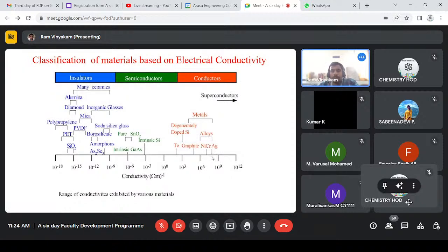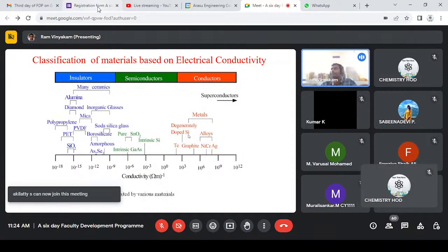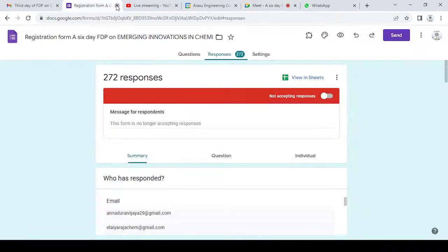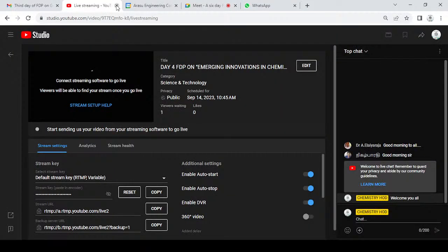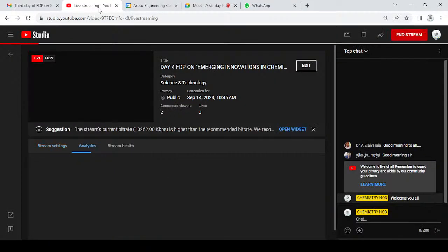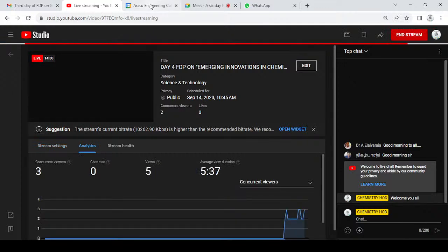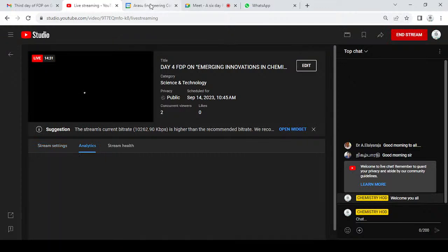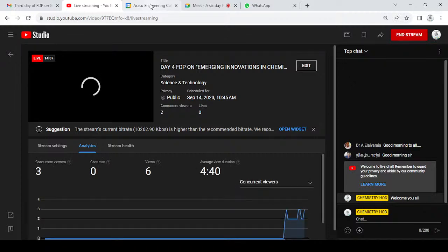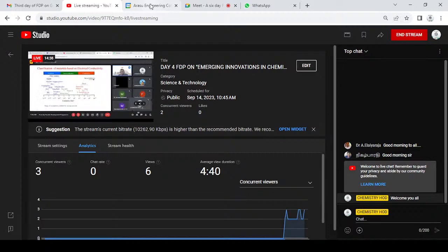Siemens per meter. And some semiconductors, as I mentioned earlier, depending upon a high percentage of doping, we call degenerate semiconductors, where the dopants come close to each other and fill the bottom of the conduction band, so they readily conduct.